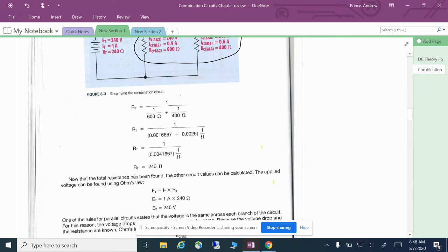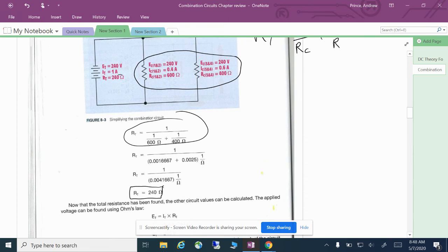you can see they've just plugged those values in here. And if you put that in our formula, this is the total. So the resistance total, 240 ohms, they're plugging in here. We had the voltage total, and from that, they've solved for the total current. So it's relatively easy for the first step to find the totals.